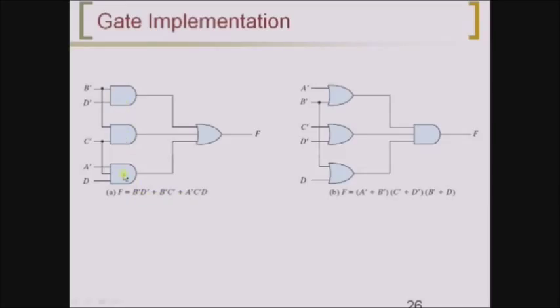So I have taken three AND gates here, and the outputs of these three AND gates should be summed, therefore I have taken one OR gate. And here we have three sum terms, therefore in order to get the sum terms we have to use OR gates, and all these three sum terms are given as input to the AND gate. Why? Because it is a product of sums.